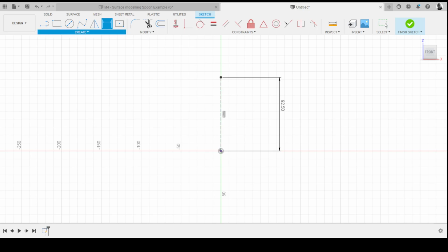And I'm going to create, the same way as before, this centre point arc, starting at this point up here, going somewhere over there, not defining that, and I'll give this a radius of 100 millimeters. A bit wonky. How do I make it symmetrical quickly? Any ideas? Have I shown you this before?